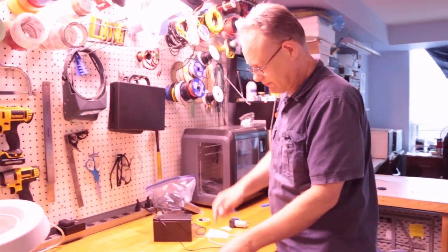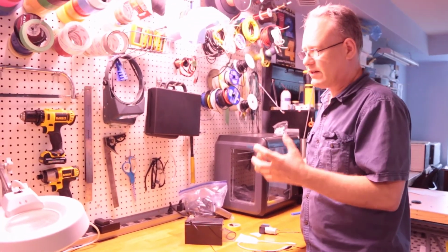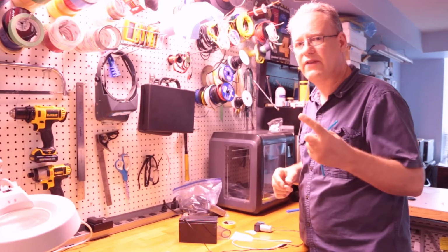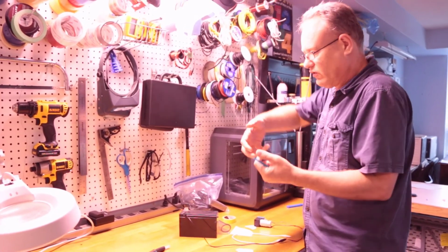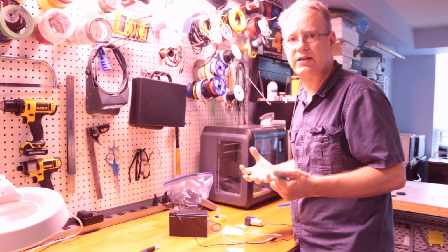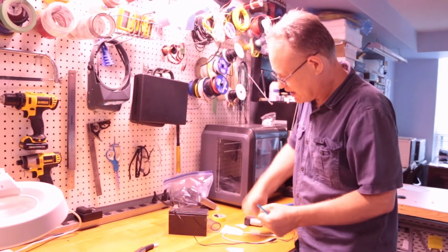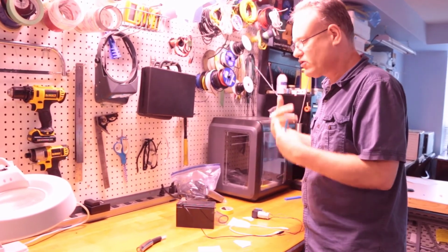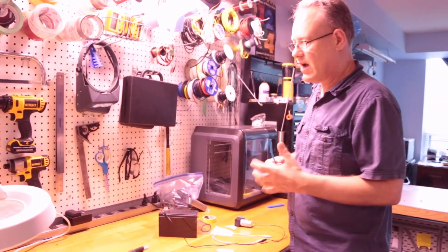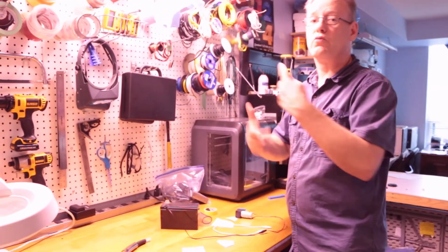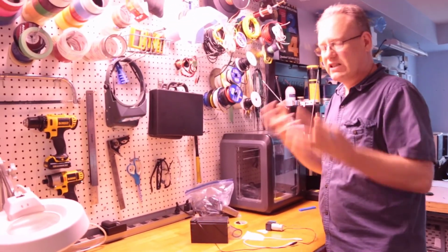But that's not how vacuum systems work. We work on the fact it's an excellent seal. Actually, you have seen vacuum systems that don't continuously suck, and those are those cool vacuum cup things that you put on glass that you can pick panes of glass up with. You create the vacuum and you pick it and it stays there because there's no leaking. So when there's more leaking, we need flow all the time, and that's sometimes why we may use a rotary vacuum generator, because it's leaking all the time.